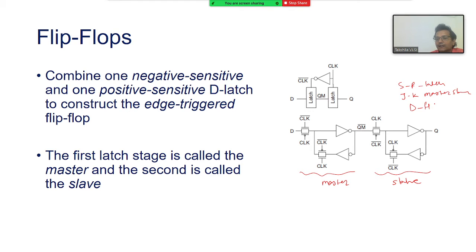In the earlier slide, I explained the D latch as just a D flip-flop because it stores one bit of information. So SR, JK, and there is one more, the toggle flip-flop T. Toggle is also a latch, right? So all these were cases that you studied. Basically they are all built from latches, which are capable of storing one bit of information.